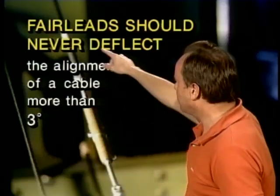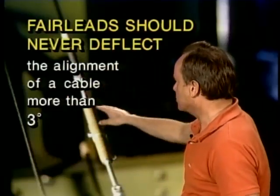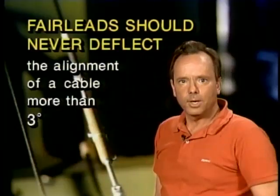So if you run the cable through a fairlead, the alignment of the cable should never be deflected more than 3 degrees. Now let's assume you're using a push-pull type control system. The threaded rod ends of a push-pull type control system should be checked for the amount of thread engagement by using the inspection hole provided.